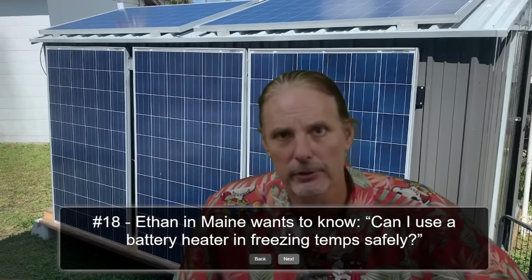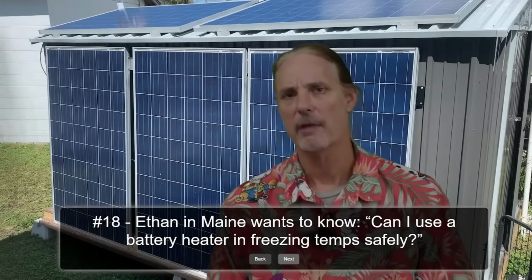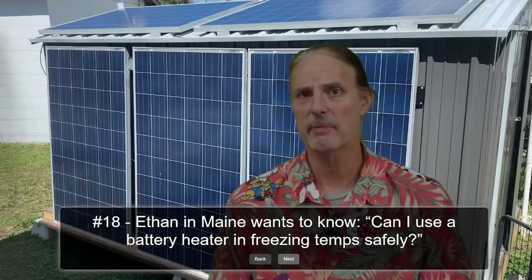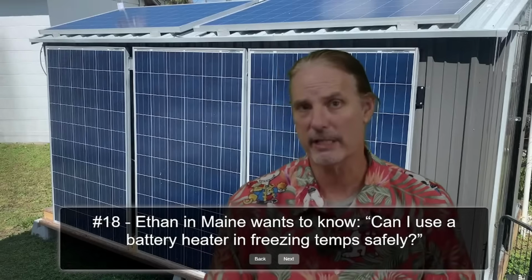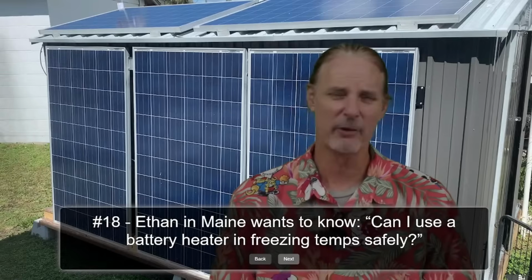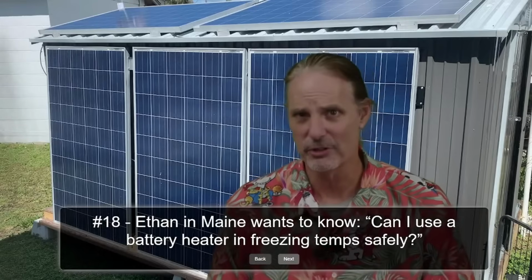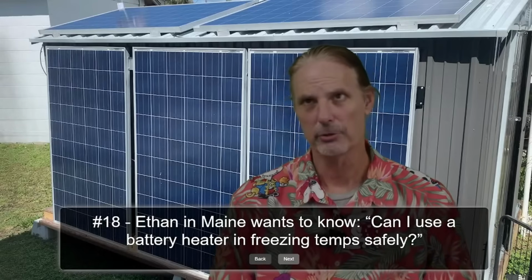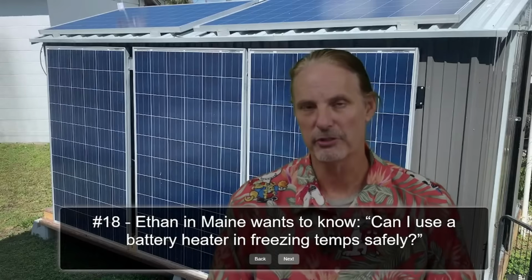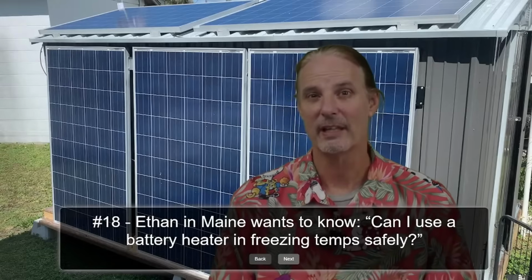Ethan in Maine wants to know, can I use a battery heater in freezing temps safely? Absolutely. I'm not sure if he means a battery heater. Most of the batteries that come today, especially with the JK BMSs if you're building the battery, come with battery heaters built into them so they can keep them warm and you can use them in cold weather. Lithium batteries do not like anything below freezing, 0 degrees Celsius or 32 degrees Fahrenheit. They should be cut off and should not be allowed to charge.